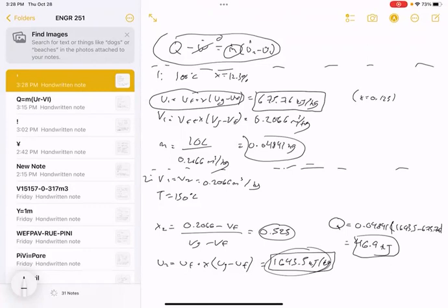In the few examples we've done in chapter 4, you can see that to change the state of a system, one of four things has to happen, or any combination of these four things. To change the state of the system, you have to do work to the system, allow the system to do work, give heat to the system, or allow the system to release heat or take heat away, however you want to look at it. But the point is, there has to be either some work or heat interaction or any combination of them. That's the only way that something can change state.